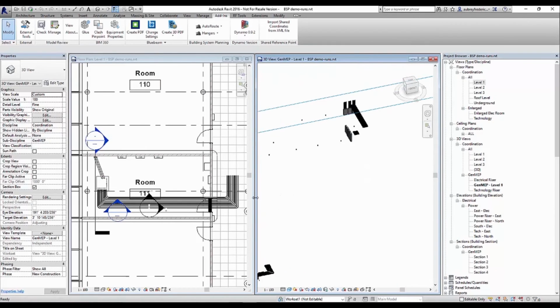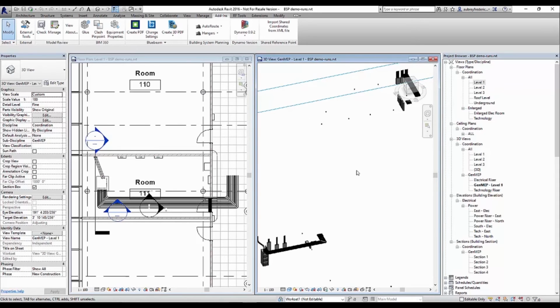Another reason for having these groups of stubs in our model is that as change happens, there are sections in my run where if I disconnect pieces of the conduit and move these groups of stubbings or stubs to different areas, when I bring in this batch auto route, it will take into account where that group of stubs is now and generate a route based on that new location. So that can be very helpful as change management starts to get implemented on the actual Revit model.